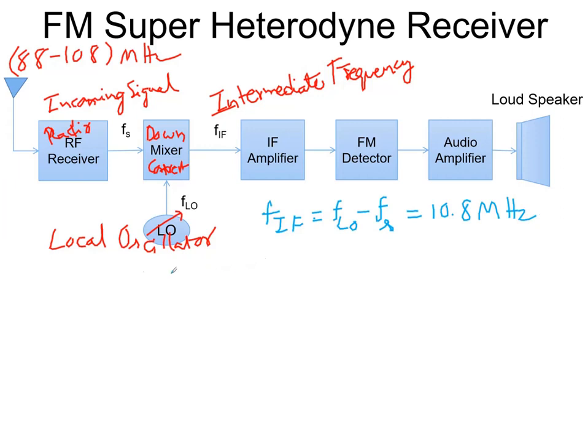And the image frequency, given by Fs dash, is Fs plus or minus 2 times the intermediate frequency. This depends on the range of operation of this RF receiver. How we will select whether it is Fs plus 2 or Fs minus 2 times the intermediate frequency.